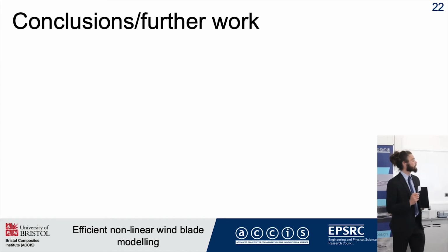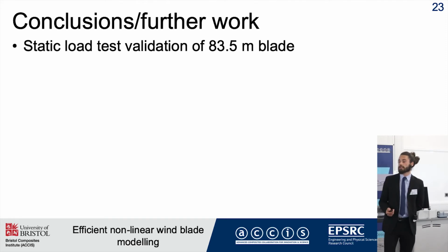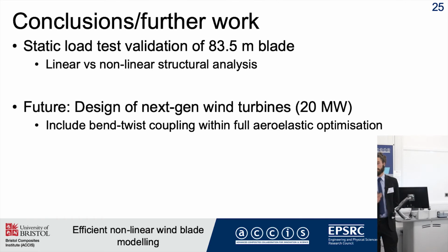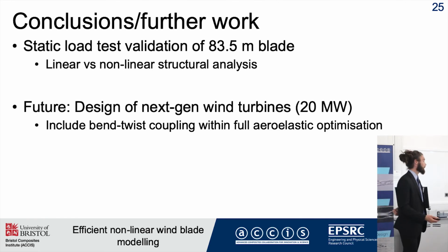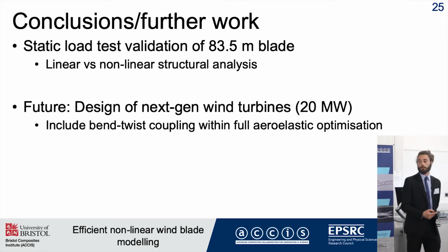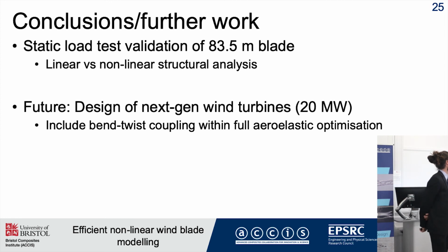So that's that, and to conclude, we've shown static load test validation of an 83.5 meter blade, linear versus non-linear structural analysis, and my ongoing future work is to go on to design a 20 megawatt turbine with bend-twist coupling within a full aeroelastic design optimization.